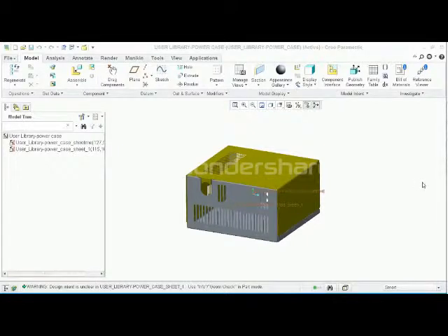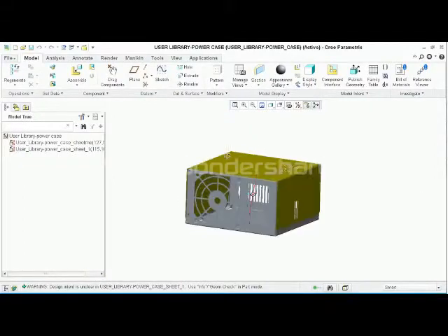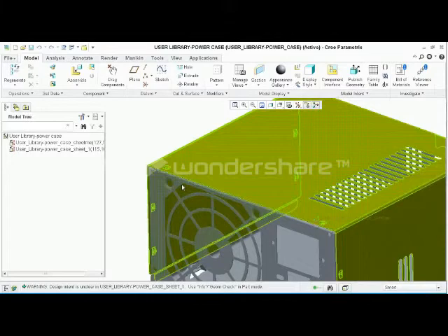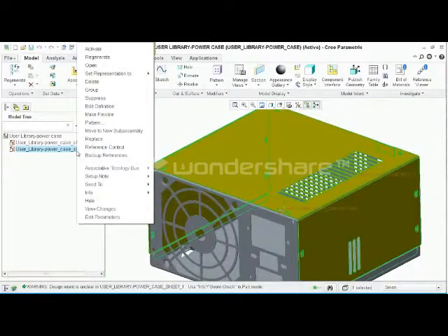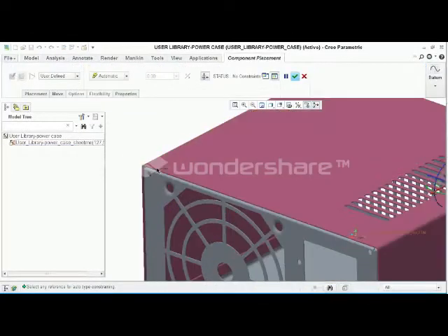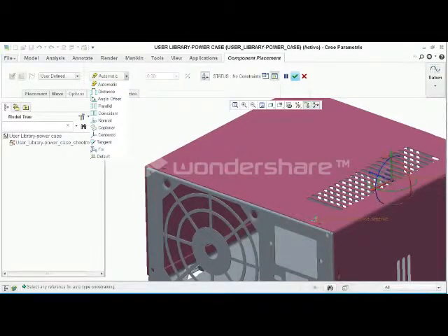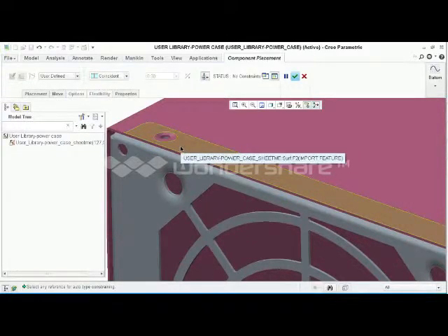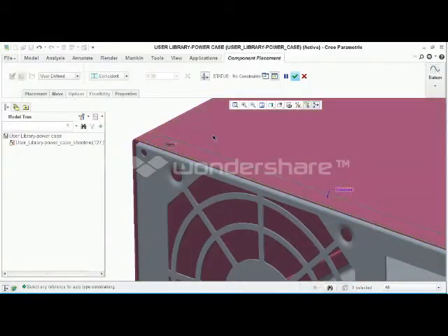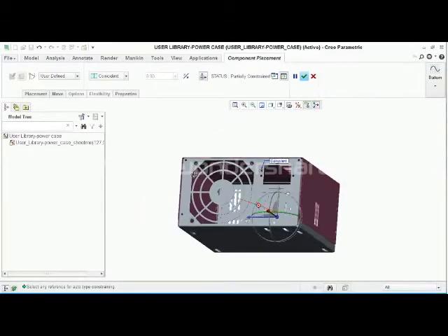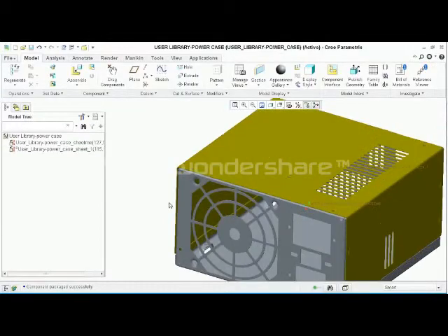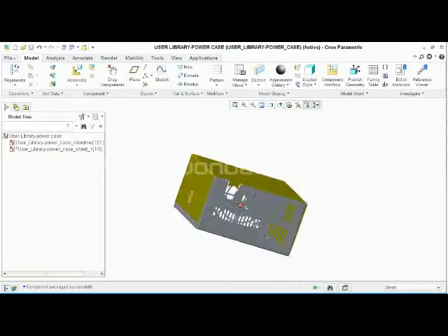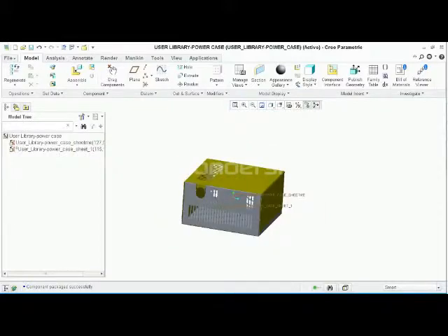First up, I'd like to make sure that this top cover sits on top of the bottom cover. So I'm going to go into Edit Definition, because this has actually been assembled. I just want to make sure that this surface right here is physically mated to this other surface, so those are sitting on top of each other. That's going to be important because I'm going to be raising the height of each of these. So the first thing I'm going to do is grab this first cover by itself and open it in a separate window. I'm going to make some pretty decent changes to this.